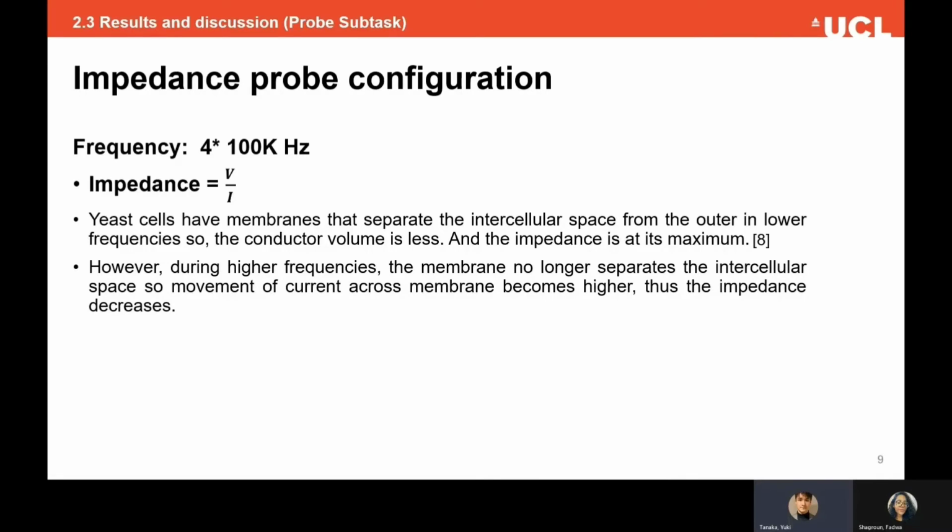We weren't able to test the values, as such we chose 400 kHz. We thought it's better to use a frequency value as low as possible, however we decided against using frequencies lower than 100 kHz, as in the real world, metal electrodes attract a counter layer of ions around themselves, which acts as a large capacitance in series with the suspension, which we suspect manifests as a large increase in amplitude in